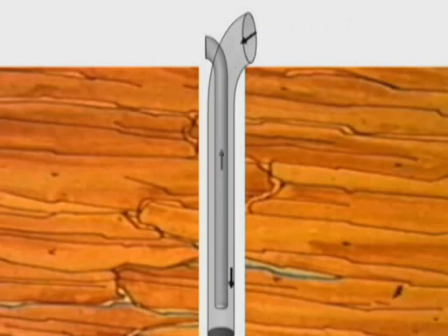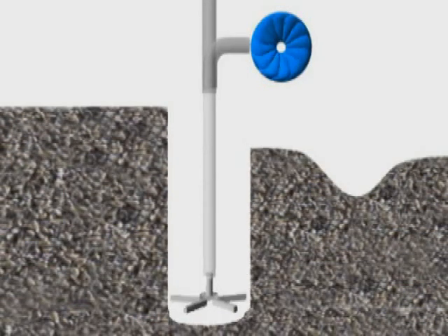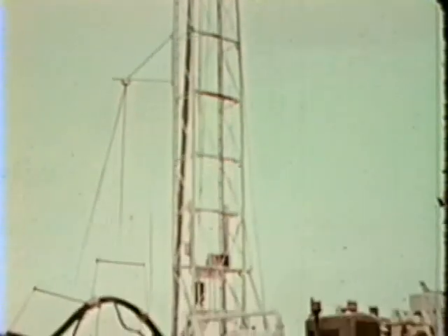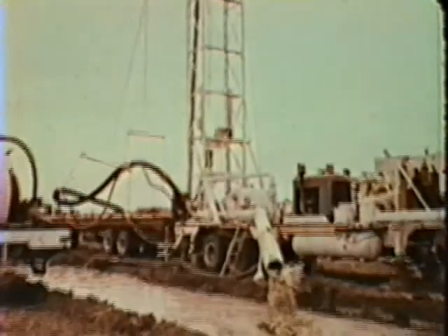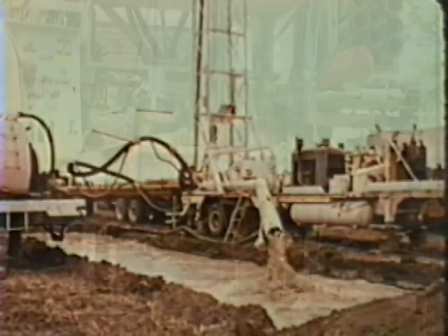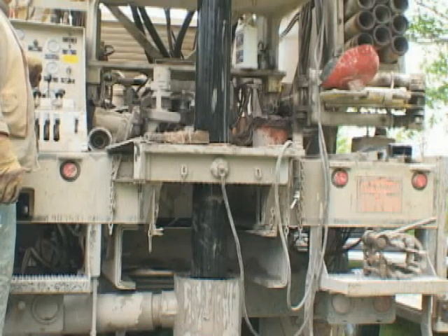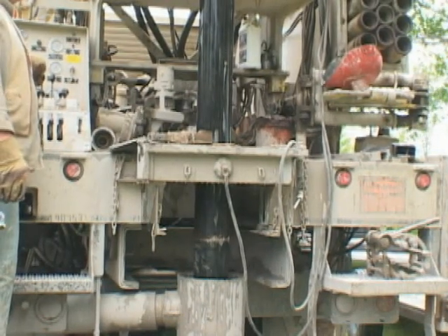The circulation path for the flushing media is dependent primarily upon the drilling system used and the diameter of the hole. The volume of flushing media required is dictated by the rate at which cuttings are produced and hole diameter, whereas the flushing media pressure is influenced by the borehole depth and restrictions within the flushing media path.